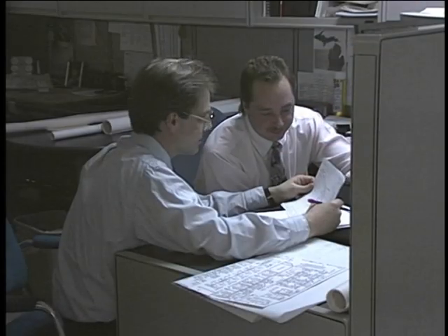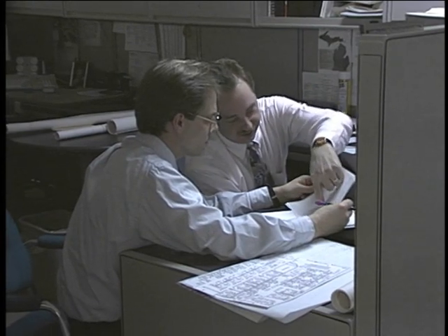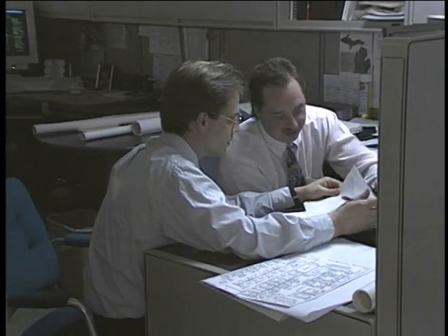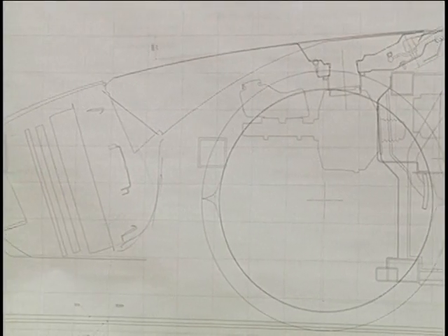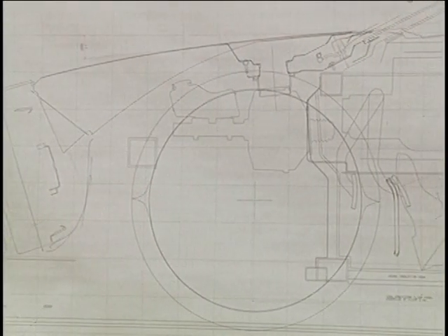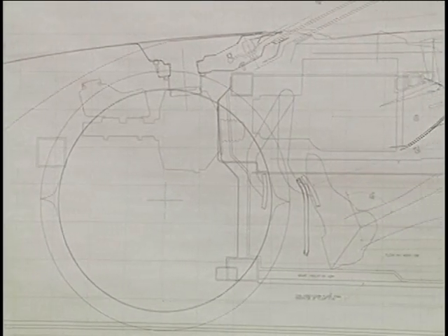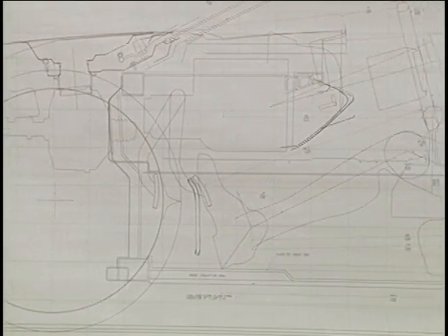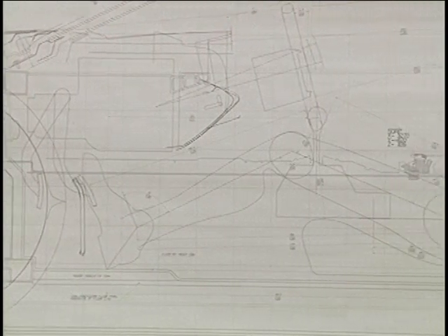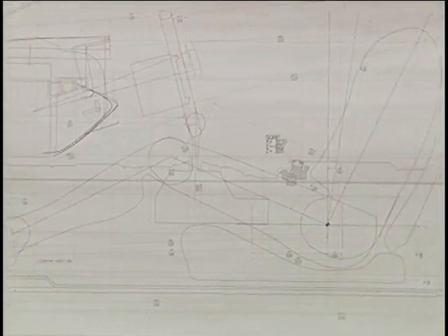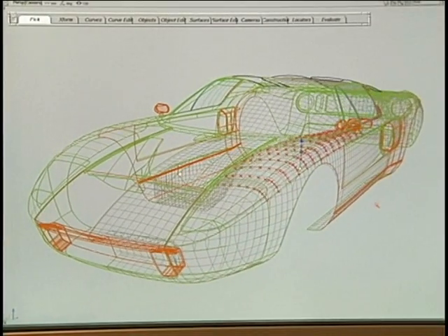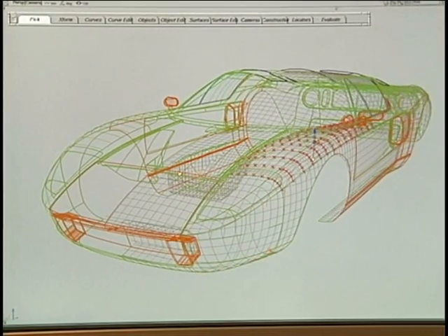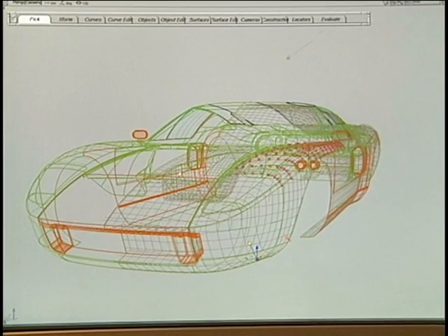The resulting surface math data from the 3D design software is constantly shared with engineering so they can package the vehicle and identify feasibility issues. Packaging defines the spatial constraints, such as headroom, legroom, and visibility, which are critical in designing the interiors and exteriors of the vehicles. Using the math data created in Alias, the design program moves into the next phase, the translation of the 3D dimensional data into the clay model.